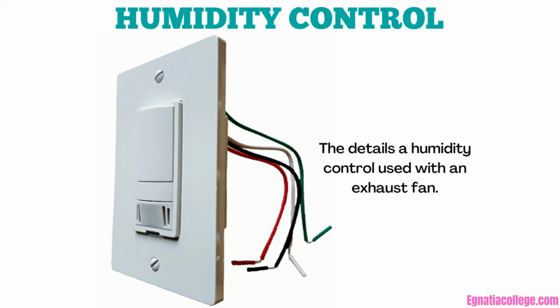However, a relay must be installed on the line voltage humidistat if the connected load exceeds the maximum allowable current rating of the humidistat. The switching mechanism of the humidistat is controlled by a nylon element that is very sensitive to changes in humidity. A bimetallic element cannot be used because it reacts to temperature changes only.